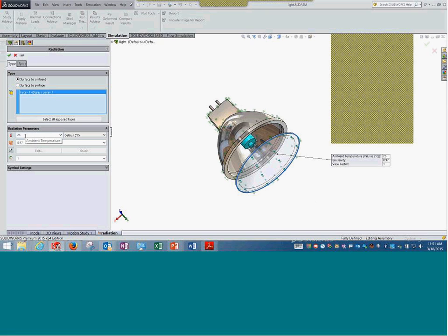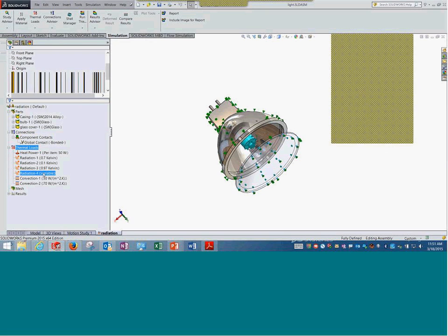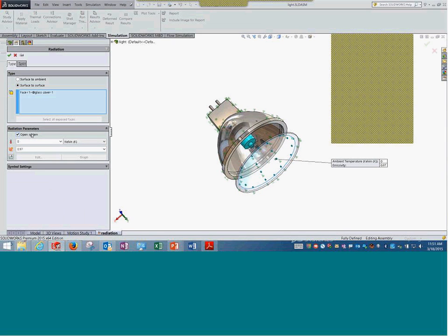There is a question which says what is an open system. So if you go here, edit, you see this button of open system. So in one way or the other, I can also correlate it or think it to be similar to surface to ambient, or going to nowhere in this sense. Okay. So in one, you are saying what is created goes where, saying the heat is being absorbed. The other one we can say heat is actually going to nowhere, or it is an open system and it goes to an entity which is not part of this setup. Even that could be the case. We can do that, and again we can see here we are showing the ambient temperature and emissivity, so that can be done. Only difference for ambient, if you see here, we can also give the view factor. That's it.